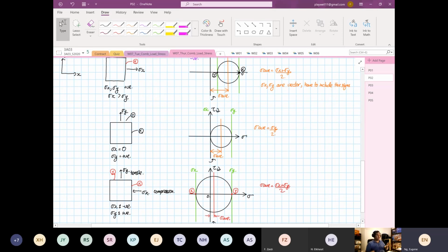Okay, so sometimes, I don't usually use this, but if you have a material that is no good in tensile, by just looking at the average stress, you say, hey, this will not work. For example, concrete, right? Brittle materials are very bad in tensile loading. So by calculating the average stress, I don't need to go any further. I'll say, oh, my average stress is positive 100 megapascal. This is a very brittle material. It's ceramic. It cannot stand tensile loading. So I stop my analysis. Does that make sense? Yeah, okay, makes sense. That's the only way that I'll use it.